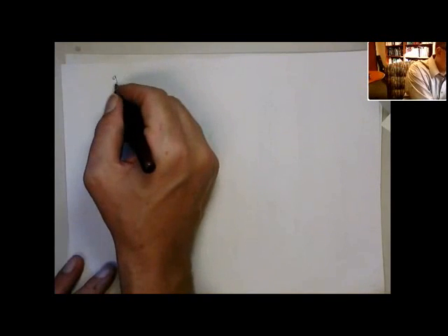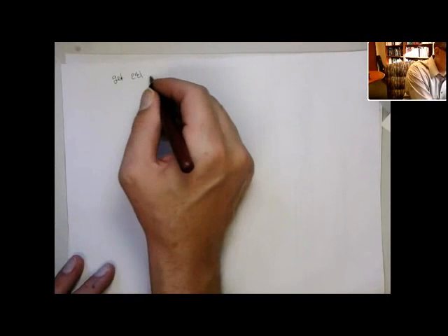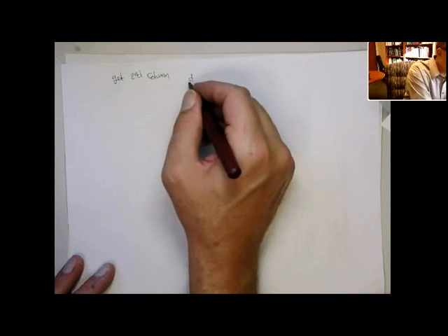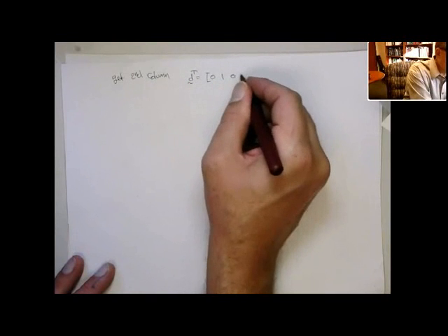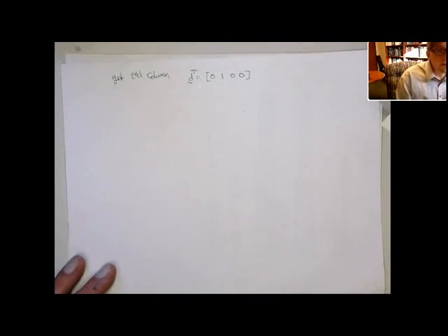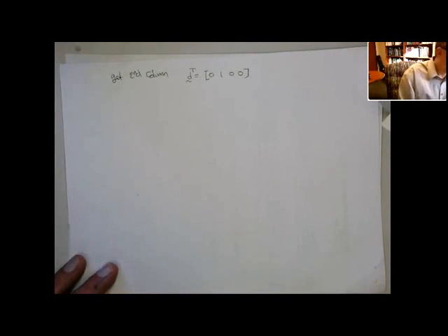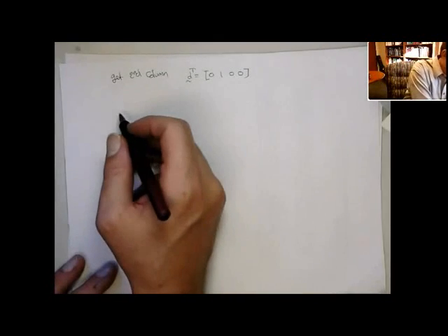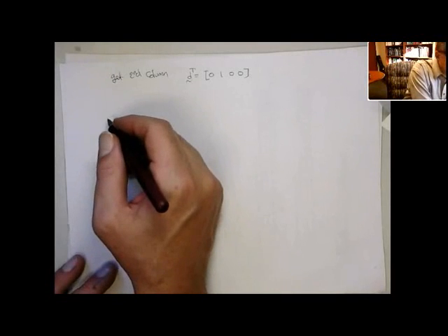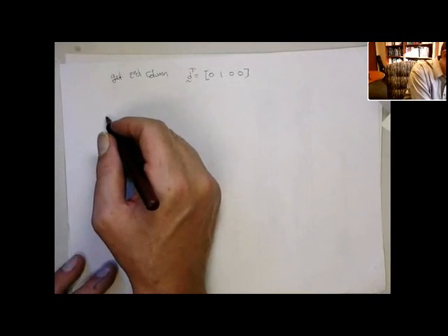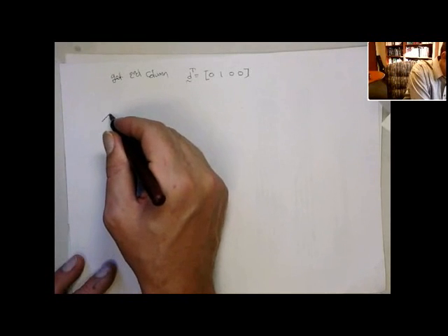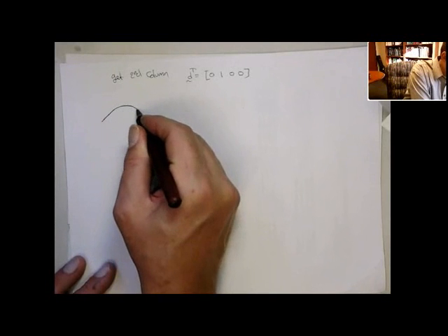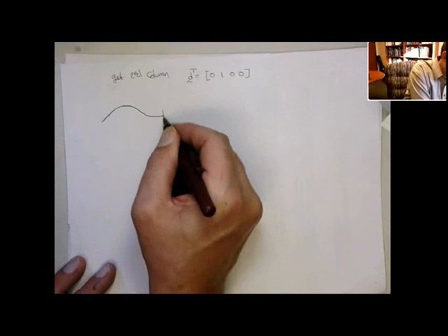This is to get the second column. And this is going to be a displacement vector. Well, let's transpose it just so it's easier to write: 0, 1, 0, 0. So it just has a unit rotation, a 1 radian rotation around the first node. Granted, it's a really big rotation, but so be it. It's good enough for the derivation. So this node rotates at 1 radian and then comes back down and is fully fixed at this point.